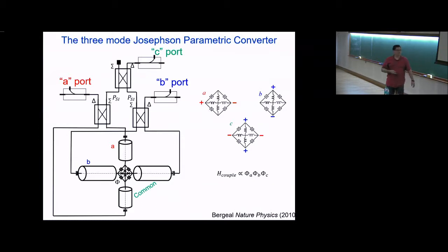So what I have to do here is to embed this guy in a microwave circuit so that I have physical modes and physical ports that connect to these 3 eigenmodes of the JRM. The way we do this is by having a lambda over 2 resonator on the vertical arm. You see that couples nicely to this B mode. I see I've labeled them backwards here. And then you have a horizontal lambda over 2 resonator, again putting the JRM at the current antinode so that we have the current flowing in the right way.